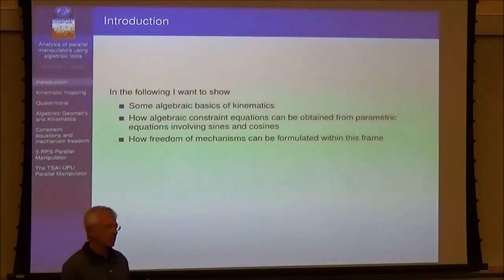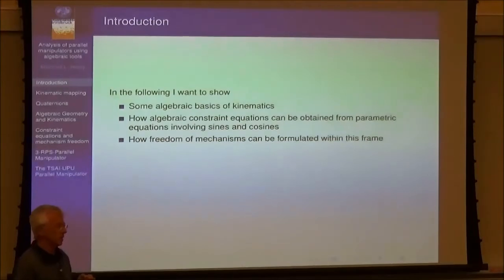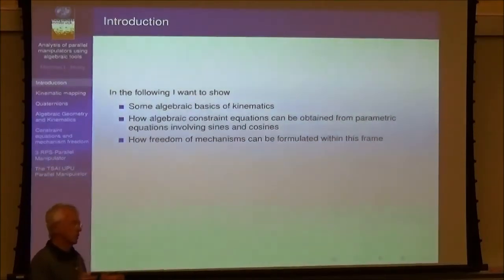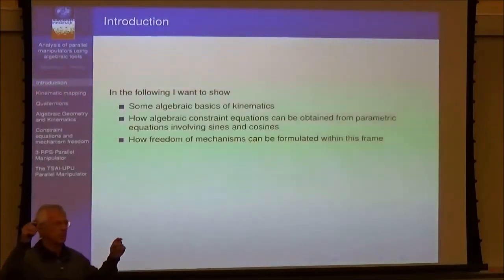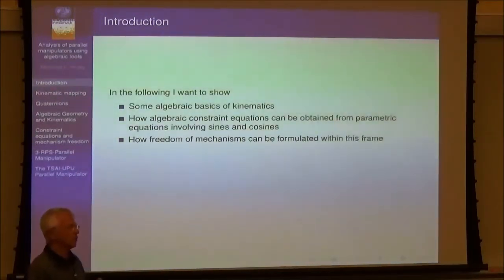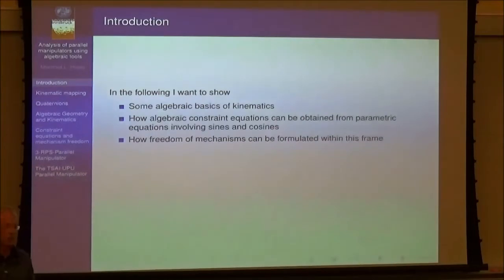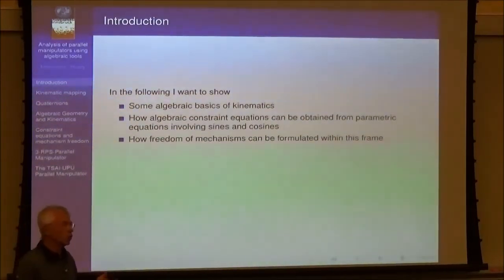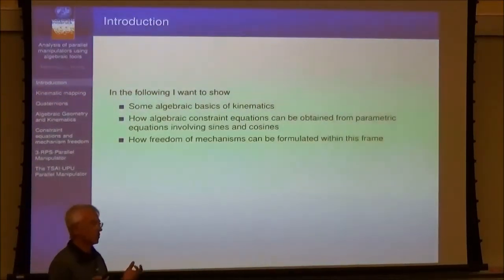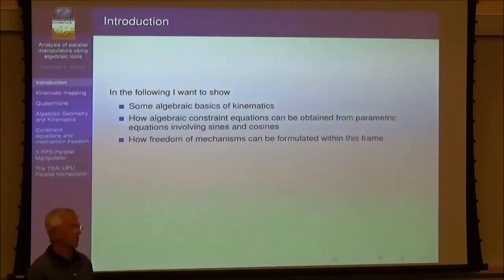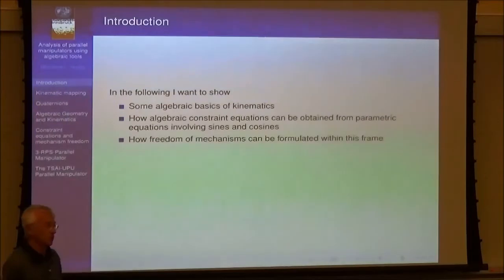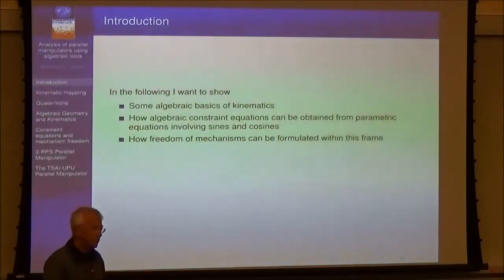It means these formulas never take into account the geometry of the system. Therefore, they give you, I would say, wrong results for certain layouts of your kinematic chain. You all know the notion of over-constrained mechanisms, mechanisms that should be rigid, but because of their special geometry, they are movable. Yeah.